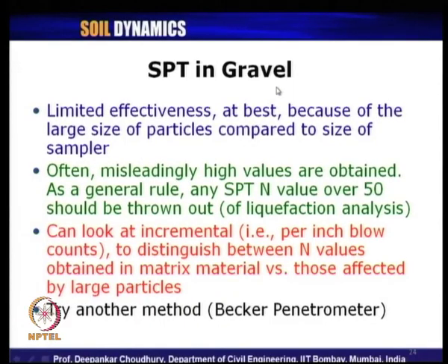In gravels SPT has limited effectiveness at best because of the larger size of the particles compared to the size of the sampler. So, many a time whatever SPT N value you get may be misleading, because whatever size of sampler tube you are using, many a time the gravel size can be bigger than that. So, it will not give you the proper value of SPT N value.